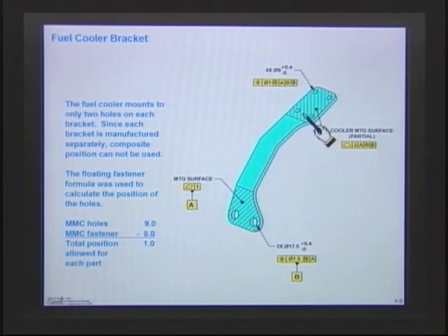Because that's where, if I was going to probe with a coordinate measuring machine or build a gauge to make sure that that fell within tolerance, I'd only want to check that area. That has to be within 3 millimeters. And what about the bend and everything else in here? Well, the angle and what arc, who really cares what that is?